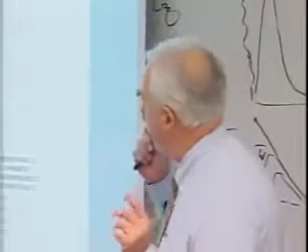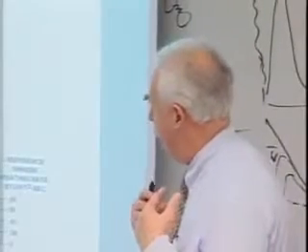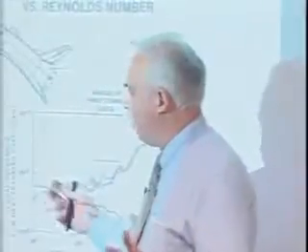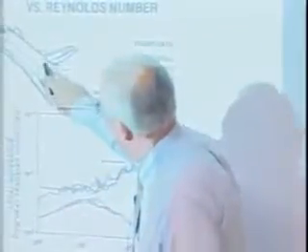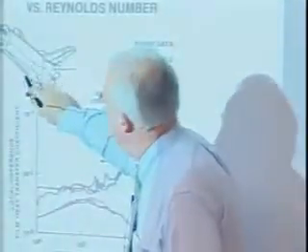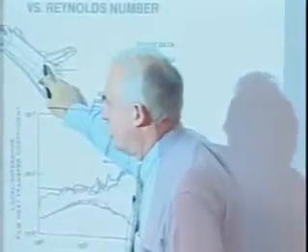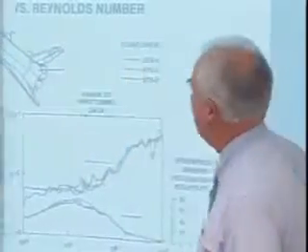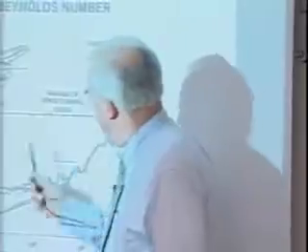By the way, Aaron, Max Fouché told me to burn a hole someplace on the lee side. He didn't want too much tile there. The only thing I was able to do was we exceeded heating here because we didn't simulate the flow very well in wind tunnel. We had to put tiles there after first flight. So I told him that was as close as we came. In any event, this is heating on three trajectories through normal shock history.